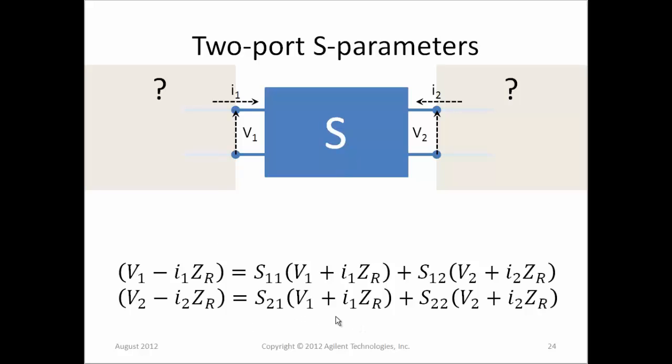In a measurement situation, the unknowns are the S parameters, and my job is going to be figuring out a way of setting these algebraic equations in parentheses to either 1 or 0 to minimize my measurement error. In a usage situation, I'll know the S parameters because I've already measured them, and I'll be solving for the V and I using simultaneous equations and algebra and so on.